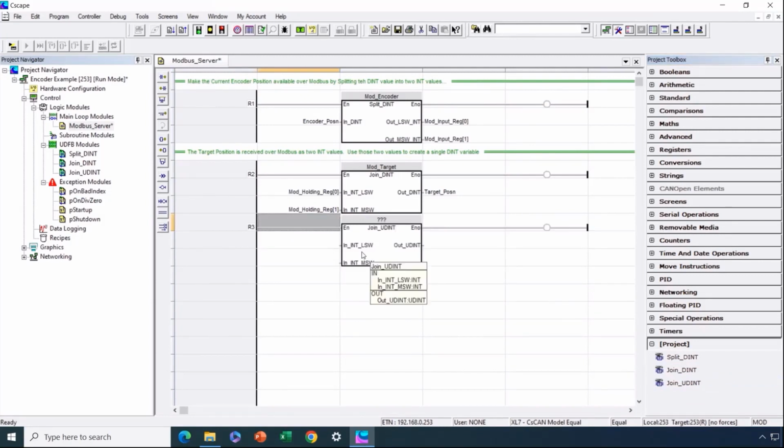And like all user-defined function blocks, they do need naming because they're each a unique instance of the other. So that is very important, of course, because it allows you to have multiples of the same UDFB just working on different variables and different Modbus data in your program. So that's how you add a UDFB to your project in Enhanced IEC.